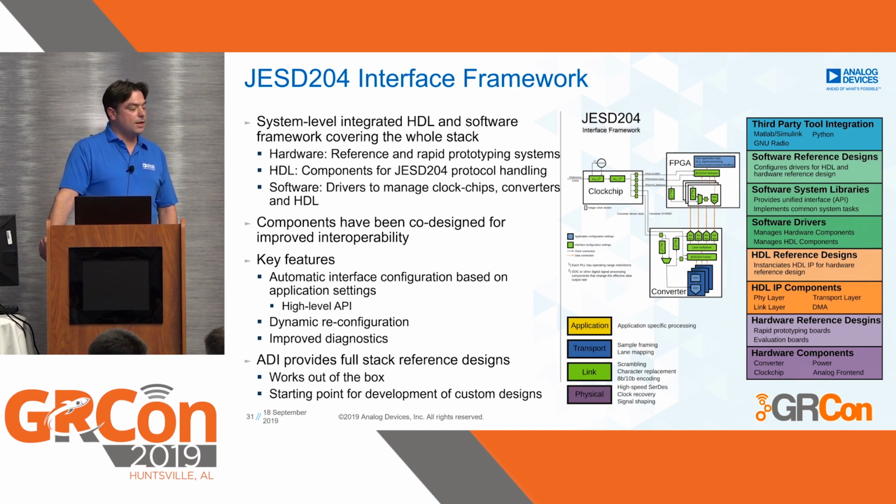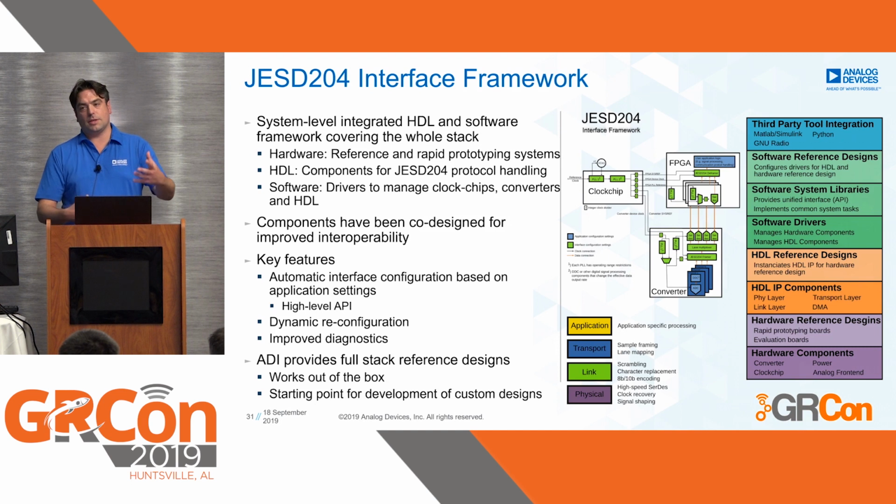It has been co-designed for improved interoperability, so it is really a framework. The key feature is that you say, I'm a converter, I have this number of converters, link parameter M, I want to use that many lanes, and I want to run at that baseband rate, and then everything is set up and configured without any other user intervention.